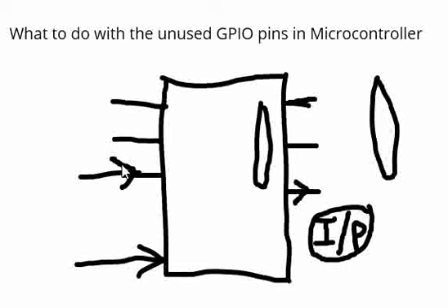Now, these input pins which are not used in the circuit might be connected with a pull up or pull down. Either of these can be used.